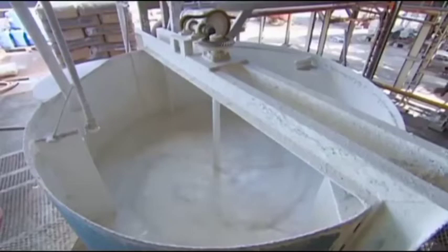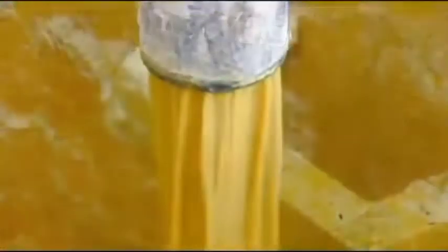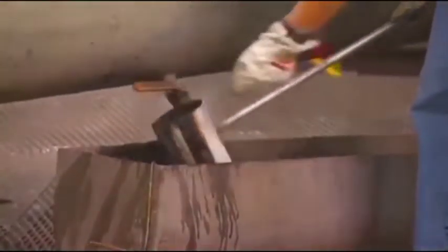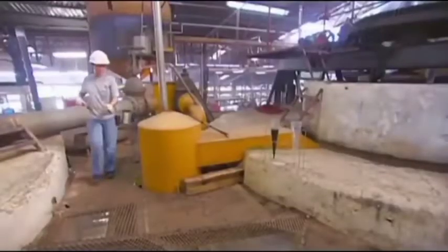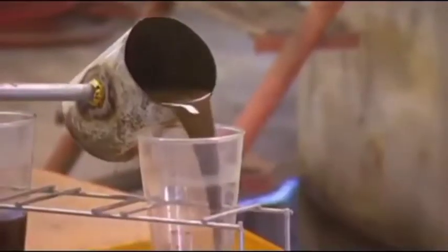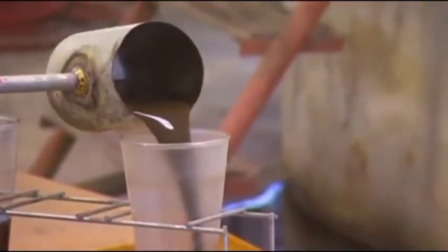3. Donnelly chute. The Donnelly chute is an input funnel to the mill, installed together with the underfeed roller or with the pressure feeder. The pressure of the bagasse at the bottom of the funnel, at the point where the bagasse will enter the mill, causes the bagasse to be pushed into the mill. The height of the bagasse in the funnel is adjusted according to the ability of the mill, about 2.5 until 3 meters. Mill. The mill is a tool for extracting juice from the cells in sugarcane fiber that have been cut by preliminary processing tools.